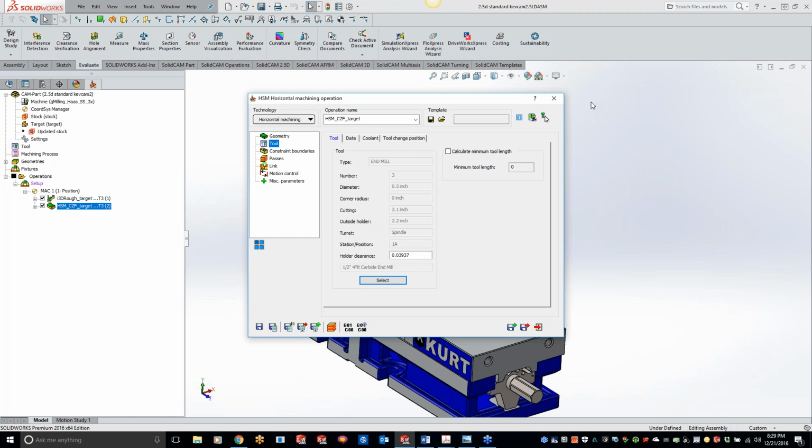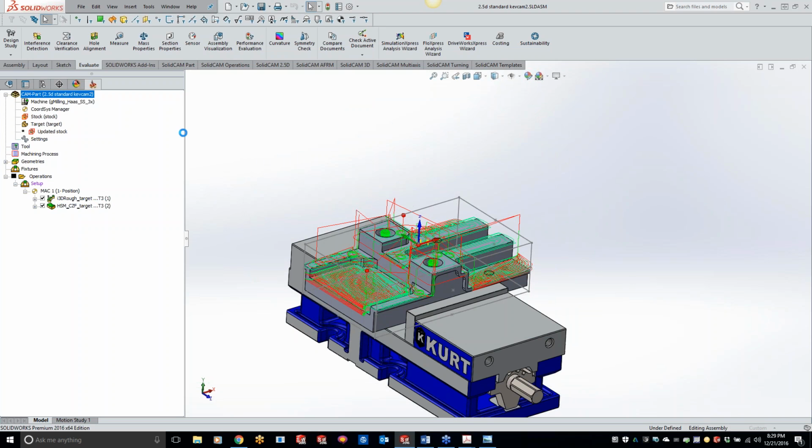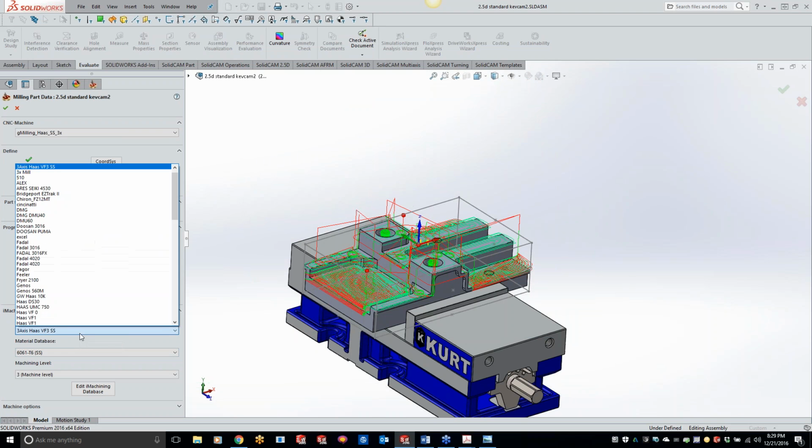And the nice thing is, I know you guys can't see the questions that are coming in, but Chris is running a Bridgeport machine. That's nice because we take into account what machine we're actually using this on. This particular one, I'm running on a Haas VF-SS. But by coming in here, I even have a Bridgeport EZ Trak right there. It's just adjusting feeds and speeds. So we know your machine by you giving us the max feed rate, max horsepower, and max spindle RPM, and it automatically compensates for that Bridgeport.